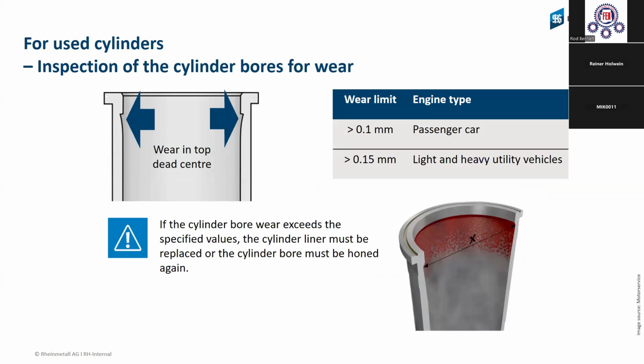This is the problem, I will say, every three months. I get a phone call from a reconditioner or private people, because when a piston or engine is running, after a while, after 100,000, 200,000 miles or more in truck application, we will have wear on the top of the liner surface. And exactly in this area, we have this wear on the top and center.